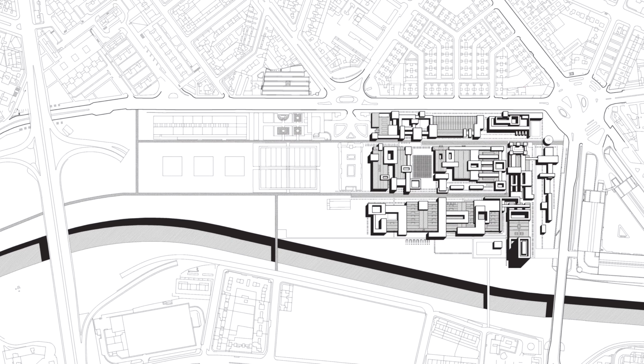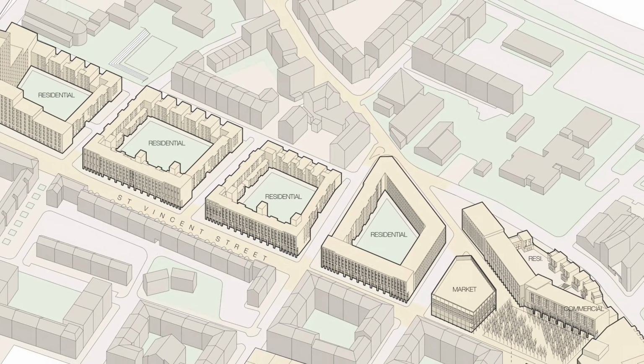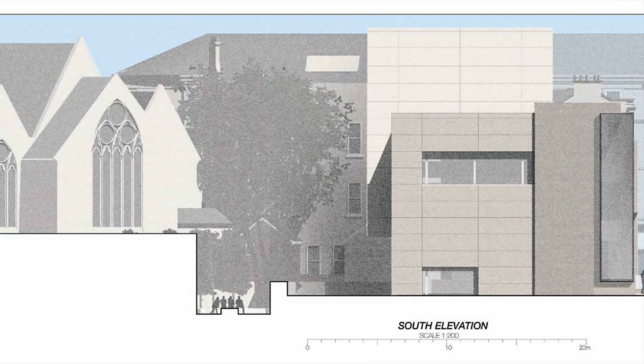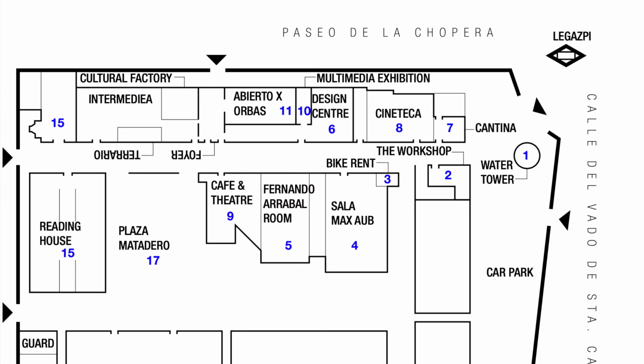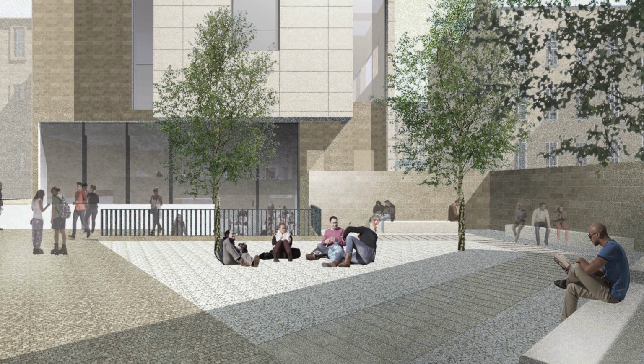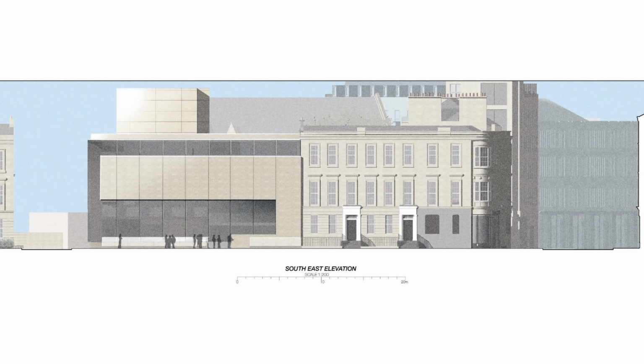Site information is critical when coming up with architectural design. This is because we need to be able to show our building in the existing context by showing features like surrounding buildings, the existing topography, various access points to the site, and also all natural features around the site. And we typically do these things through drawings like plans, elevations, and sections.